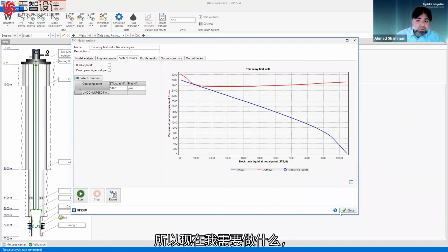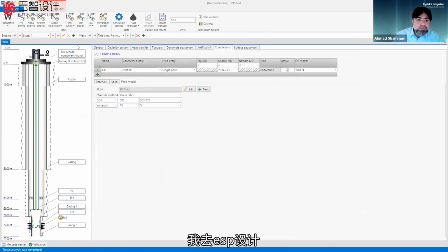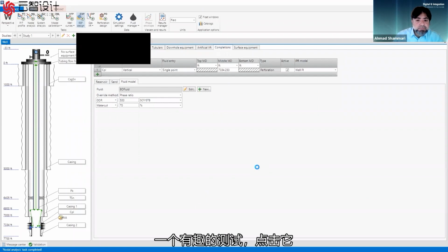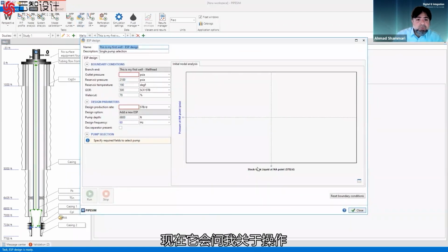So now what do I need to do? I need to install a pump that will bring back my production to, for example, let's say 2,000. So how do I do that? I go to ESP design, an interesting task. Click on that. Now it will ask me about the operating conditions.